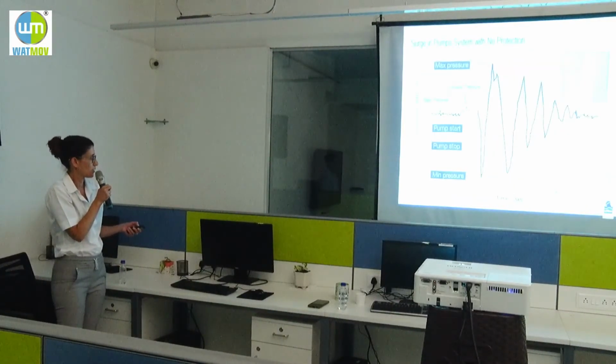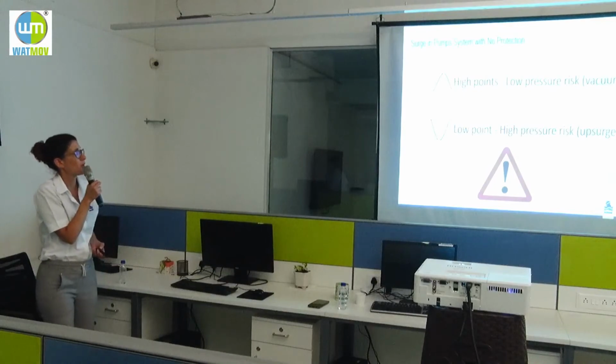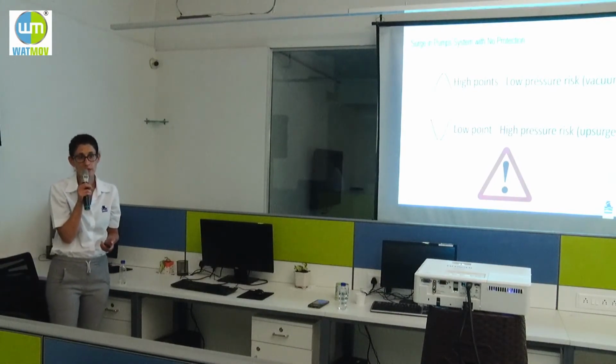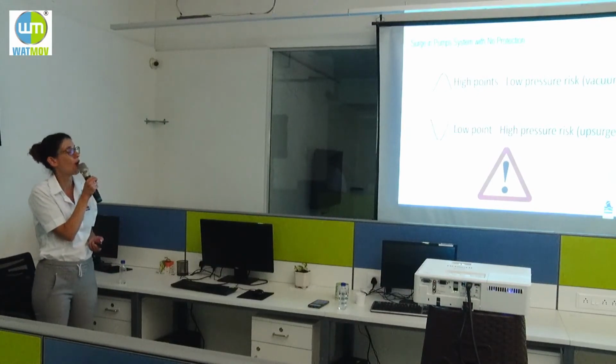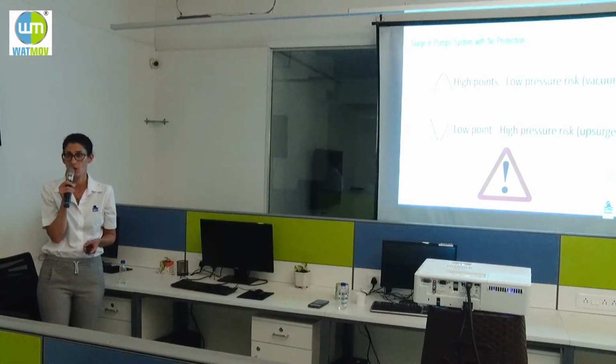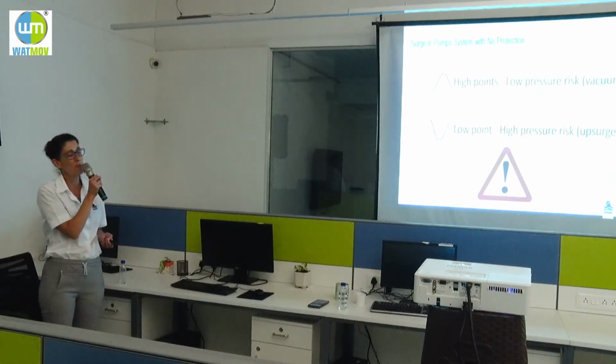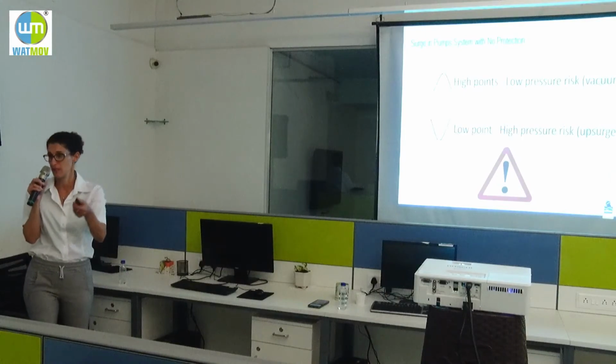I want to emphasize that high points in the line will suffer mostly from vacuum conditions during the surge, and low points will suffer from the positive wave.